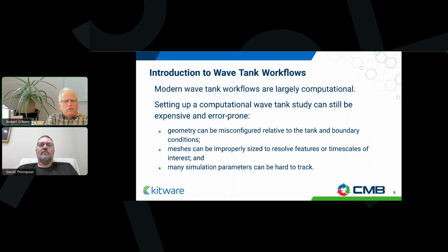If you don't have your meshing sized properly, you might miss important features or timescale issues of interest. And anyone who's run numerical simulations, as well as things that involve mesh generation, knows there are a lot of parameters that typically have to be set up in order to appropriately model the scenario that you want to deal with.